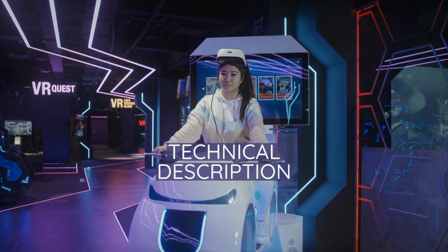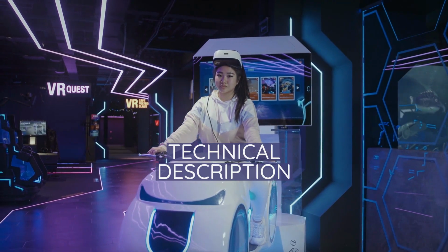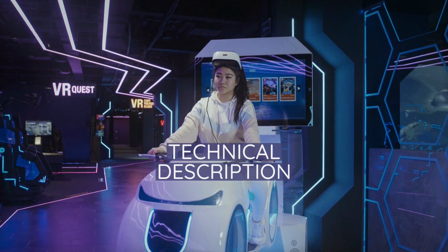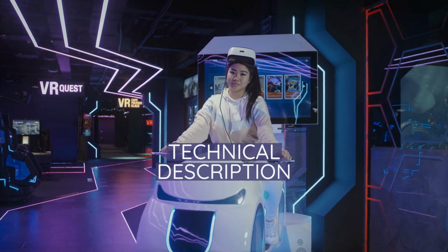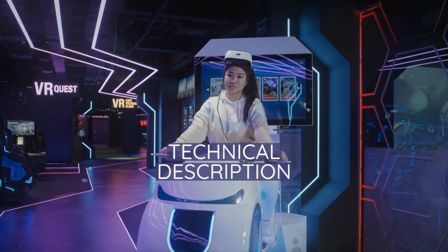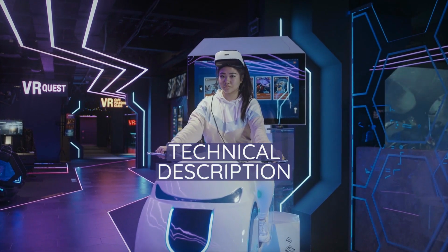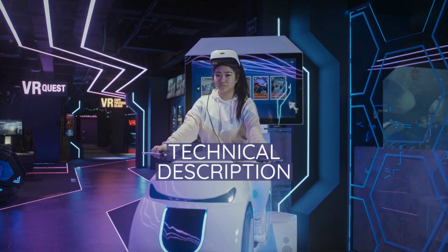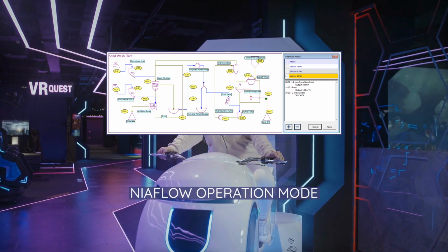Now let's delve into the technical details of this remarkable software. The calculation in NIAflow follows the flow of the material through the plant. When the plant layout contains closed circuits, NIAflow will repeat the calculation until a stationary condition is reached. During calculation, user-selectable limits are being watched, e.g. maximum tonnage throughput. NIAflow raises an error when those limits are exceeded.